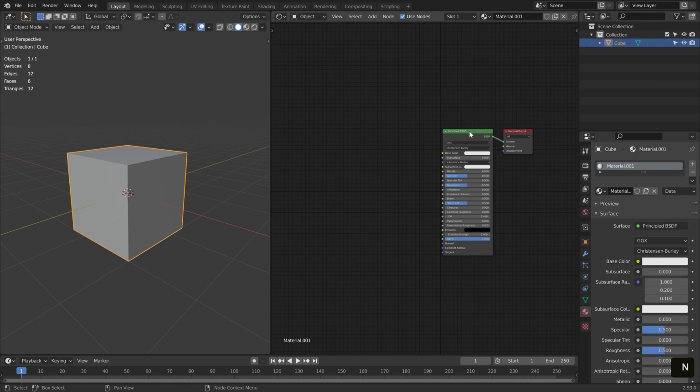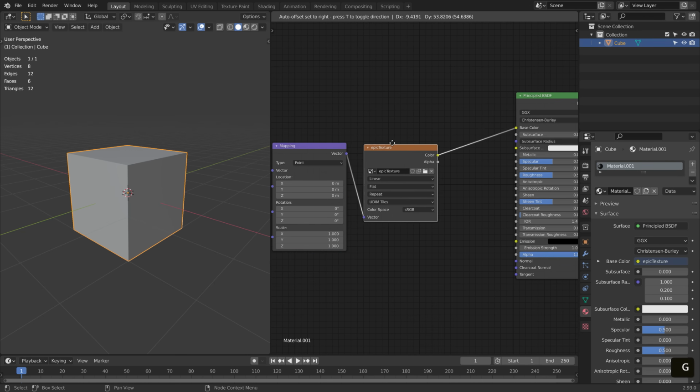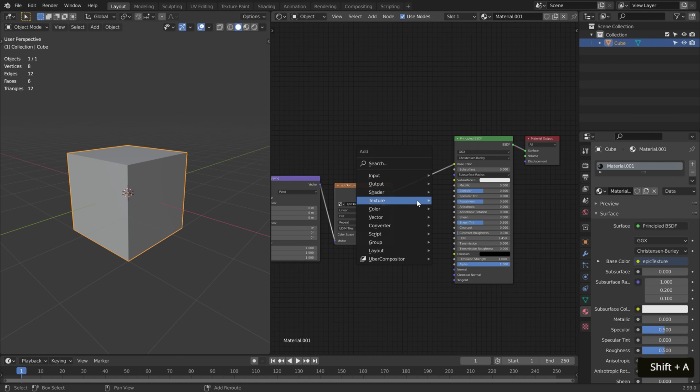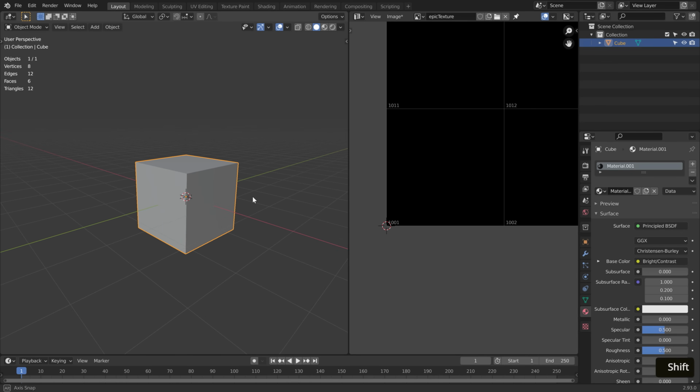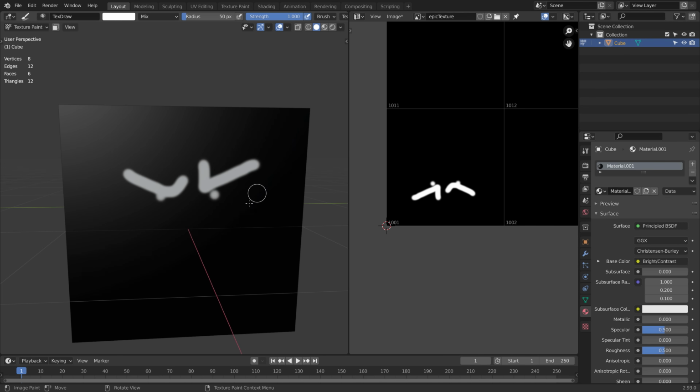Lastly, you can create a material and load your image sequence in the texture node. As you can see, although we have multiple files, it behaves as a single texture, and we can see at the bottom that the UDIM tiles are on. So you are able to layer things in the node editor or modify the texture procedurally. Finally, you can go into texture paint mode and start painting. From here, you can work as you traditionally work without UDIMs.